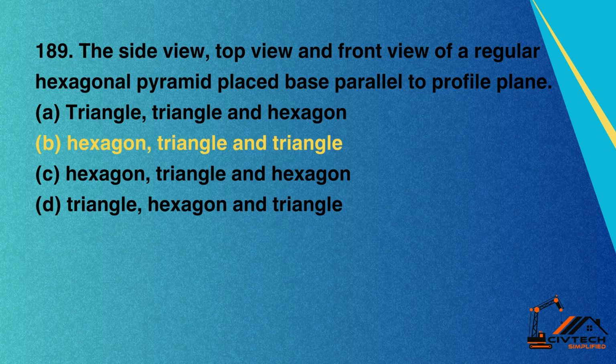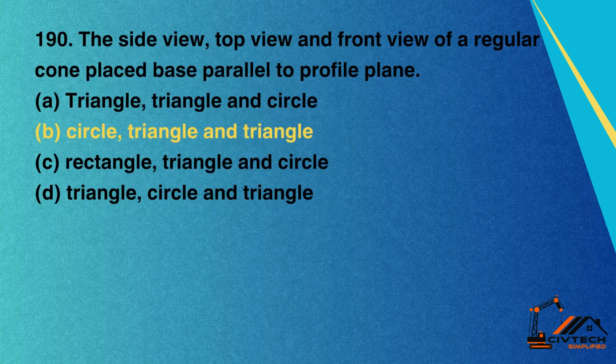189. The side view, top view, and front view of a regular hexagonal pyramid placed base parallel to profile plane. A. Triangle, triangle, and hexagon. B. Hexagon, triangle, and triangle. C. Hexagon, triangle, and hexagon. D. Triangle, hexagon, and triangle. Correct option: B. Hexagon, triangle, and triangle.